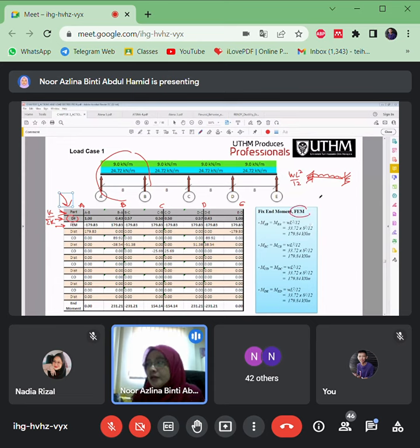The W here is based on the maximum load, so it should be based on 1.35 GK plus 1.5 QK. That's why we use 33.72. The same goes for the other spans. Is it positive or negative? Because moment has positive and negative. Let's say bottom positive, top negative. So we have a positive moment and also a negative moment.